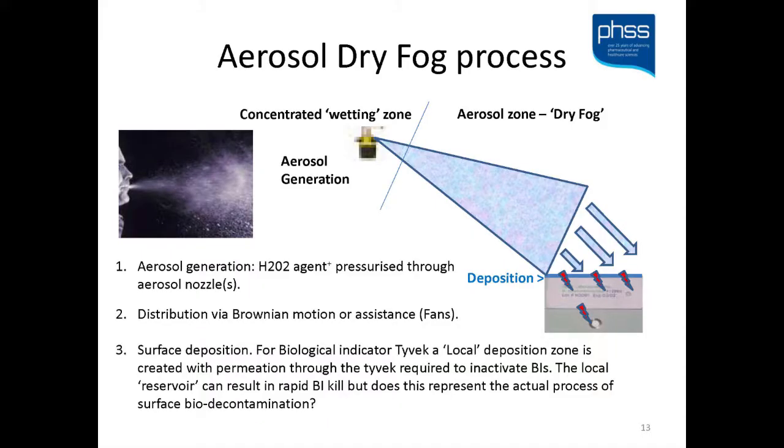Most of the challenges in all that we deal with, and all the process integration, is two main issues. One is managing a condensable vapor, not treating it like a true gas, and the other one is distribution of that vapor in the volume. If you can, in engineering and science, manage those two things, you're going to get some short cycle times. So these aerosol molecules trying to get through HEPA filters start to limit the boundary of decontamination as well.